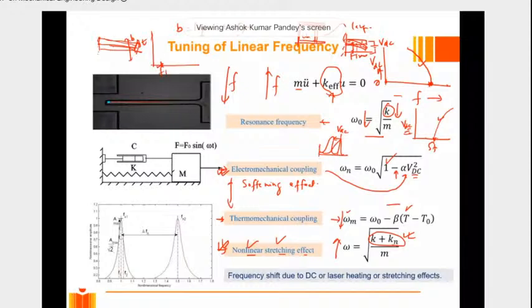We can call it out of plane. Because B is more and thickness is small, the motion along the thickness will have lower frequency, so we will call it the out of plane frequency. And the motion which is along the width, we'll call this in plane motion. That will be higher because along this, B will act as thickness, right? And since this is bigger, its frequency will always be higher. So let us say in plane will come here.